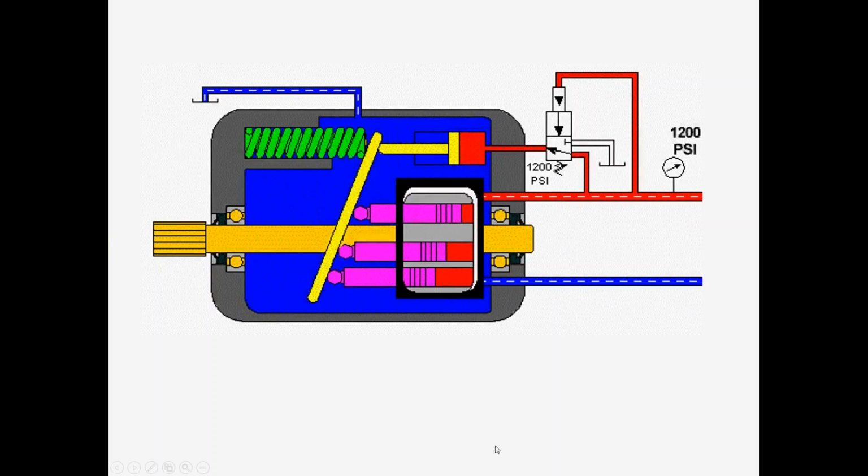the swash plate. Okay. And if the system pressure drops, and that of course would happen if we started another actuator moving and demanded more flow, then the pump would stroke a little bit further to maintain this pressure. If we close the valve and reduce the demands of the system, then our pressure would start to build. Well, we're going to de-stroke again, and that would reduce the angle of the swash plate to limit the flow.